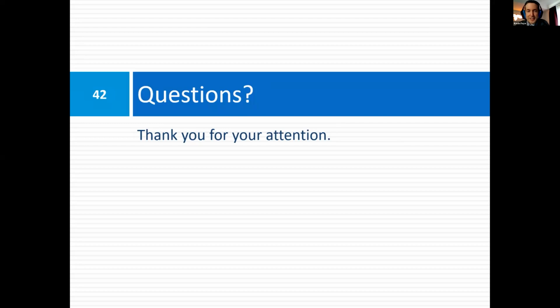That's a great question. So they're actually related. When these designs have typically been done for other sites, the prevailing practice is that you will construct a cap, typically using some prescriptive guidelines for how you will slope it and proportion it. And then you will use what is known as the institutional control period to look and see if depressions are forming. And if they do, you go out and you fill them so that the cap drains satisfactorily again. And so that is kind of the state of practice typically in this business.